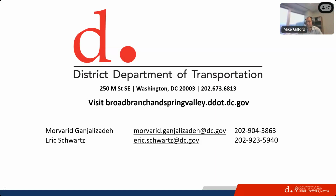Just one thing to add. I mentioned geotechnical testing. It basically tells us about the soil underneath. So we don't just pick a location to put the facility. We put it in a location that has good soil. So if the soil is good and infiltrates in a timely manner, then we put the facility. That's why we think that this is going to drain within the 72 hours, because the soil is good as well.